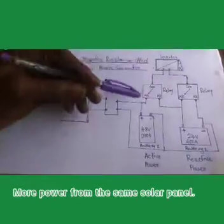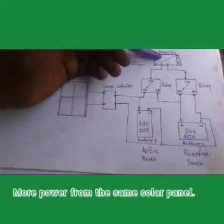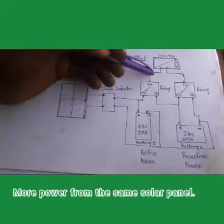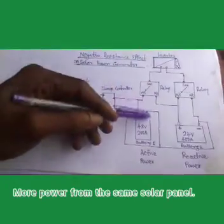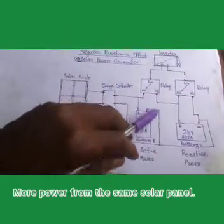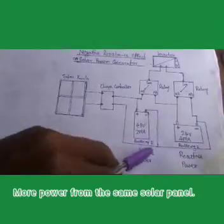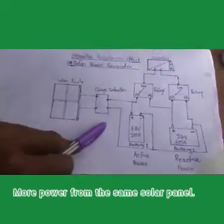Now watch what is happening. The positive terminal of your inverter goes to the common. The negative terminal goes to the common. Now from this diagram you can see that the negative terminals of the two batteries are joined together, even to the charge controller.